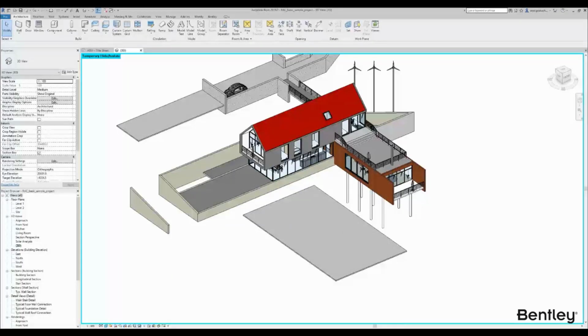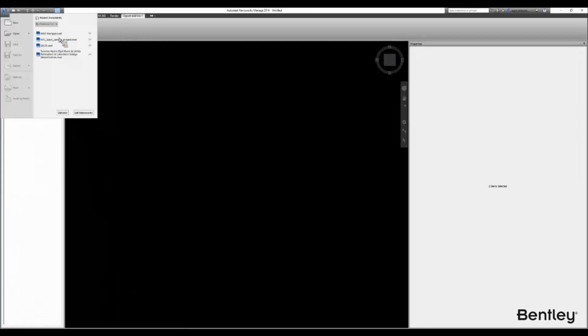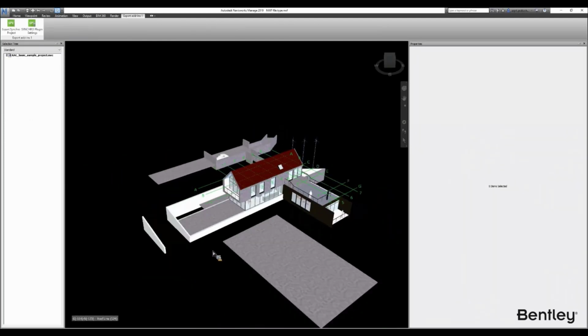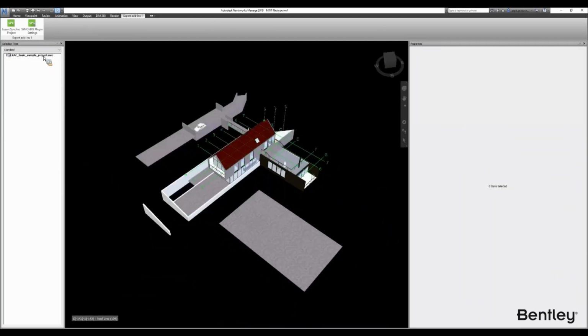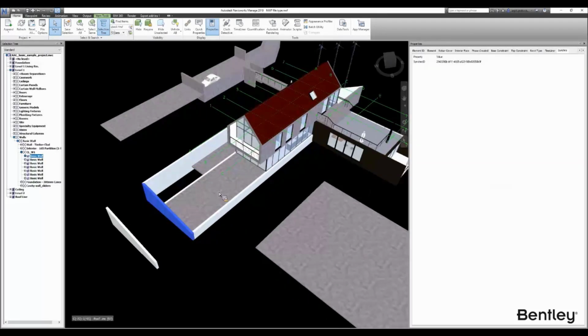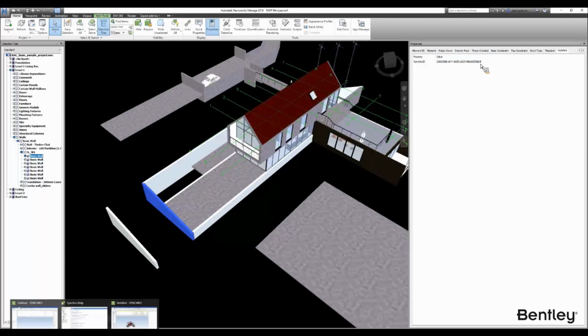All right, perfect. So if I reopen that Navisworks file, you can see all the changes made to the file. Since it was referenced, it automatically refreshed. If it doesn't refresh, you can click on refresh. If I click on this wall element, we moved the wall from its original location to this one. We see that the Synchro ID is still assigned to that, and we can cross-check with our Synchro model. So this ID is ending with B9F.